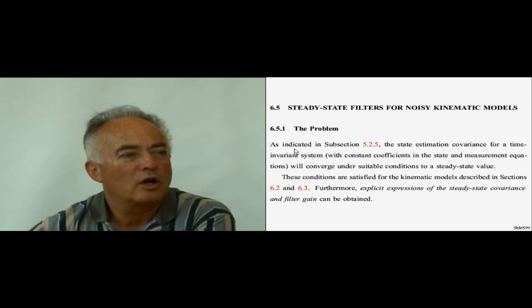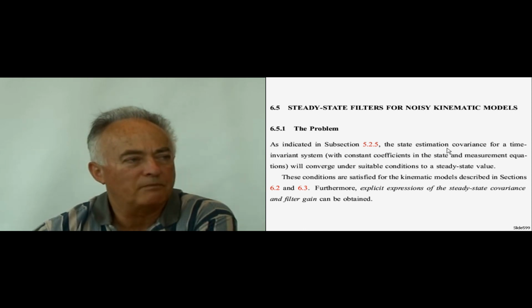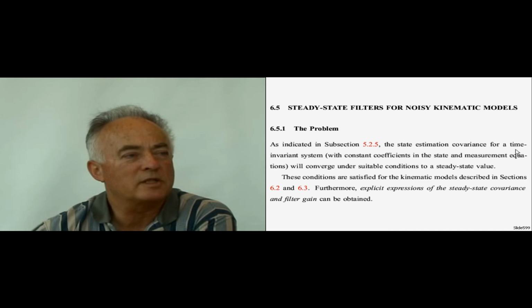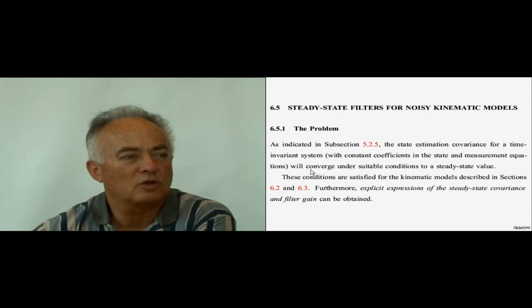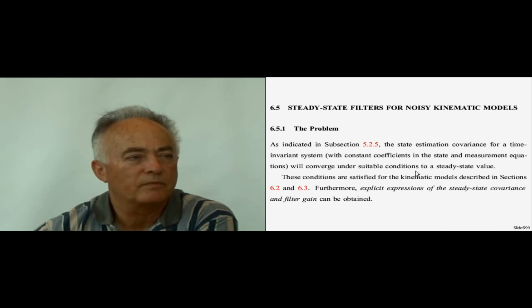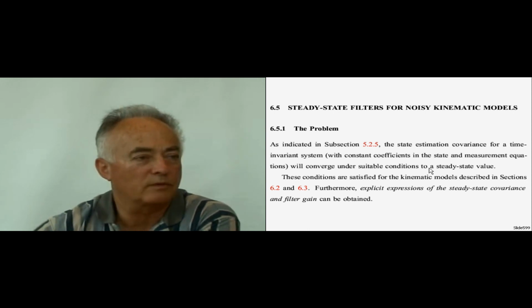So, if we have a state estimation problem for a time invariant system, namely the transition matrix is constant and the measurement matrix is a constant, we found the conditions under which the steady state covariance will converge and will give a unique steady state solution.